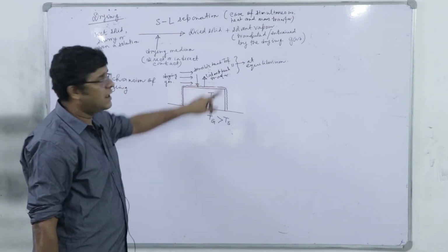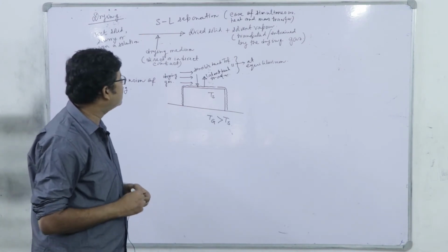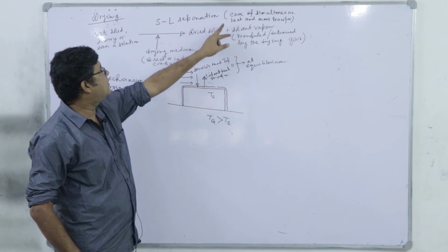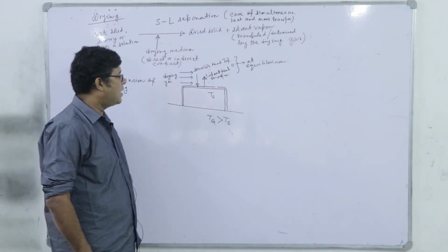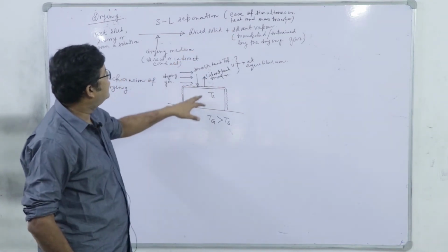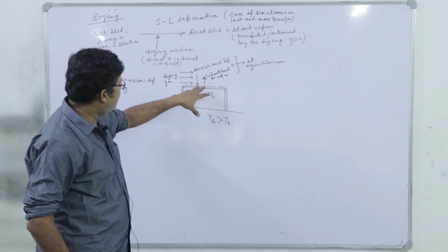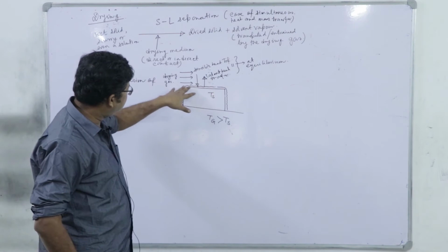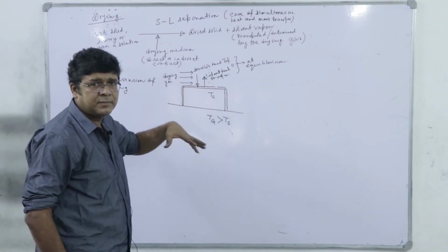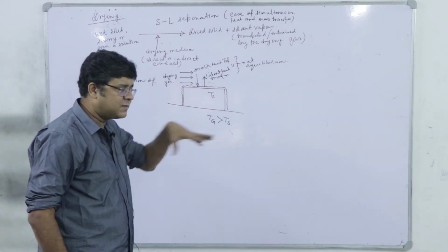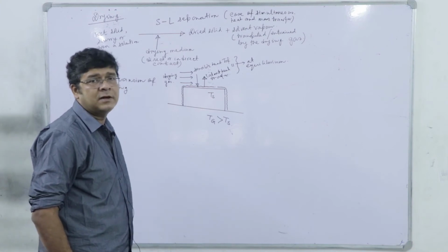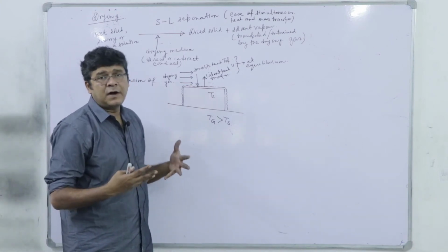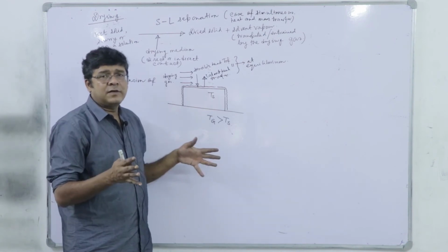So latent heat transfer is always facilitated by mass transfer. So you can understand that it is a combined or simultaneous case of heat and mass transfer. Next, you see, what are the steps? When this film dried up, first dry spots or patches will appear on the external surface of the solid. And if we continue further, still that will also be dried up.